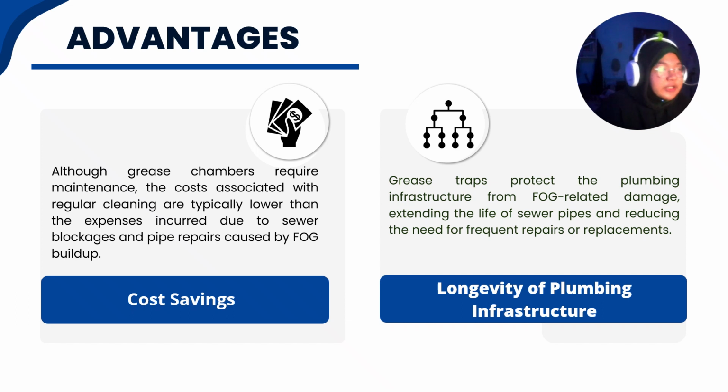The other advantage of the grease chamber is that we can save costs. Even though grease chambers require maintenance, the costs associated with regular cleaning are typically lower compared to the expenses you would need to repair sewers because of blockage or build-up by FOG.